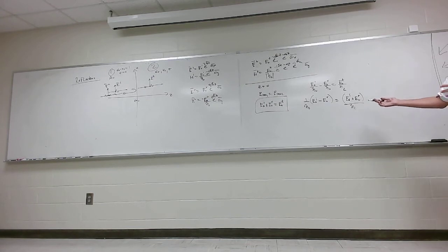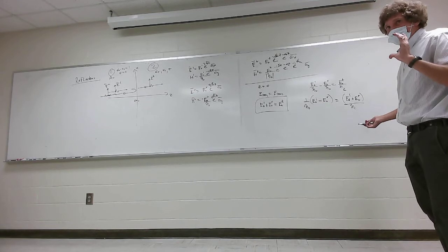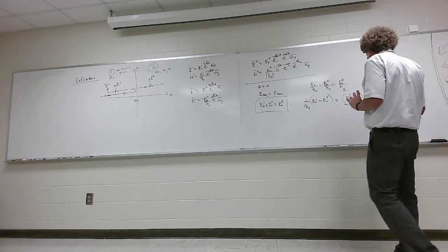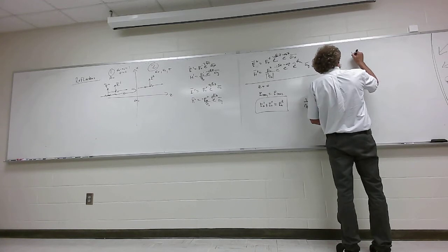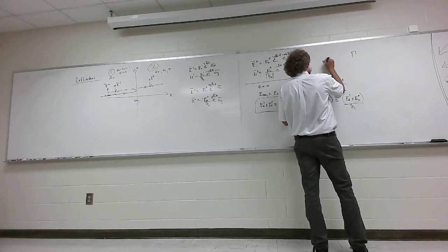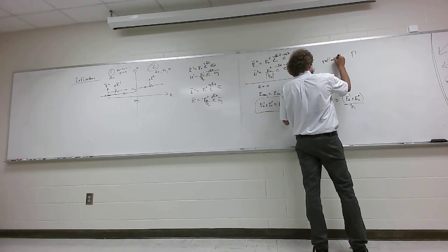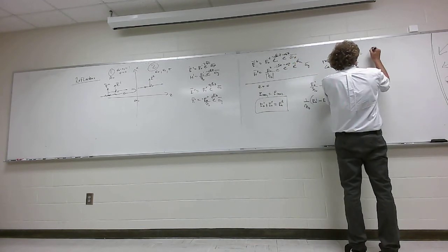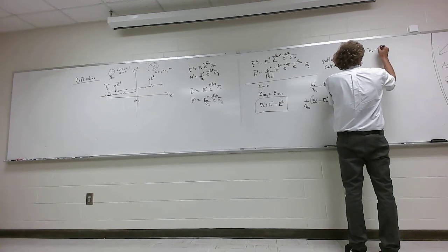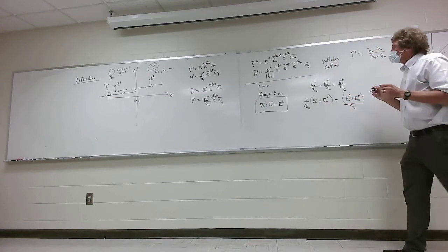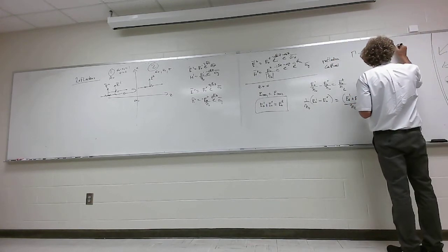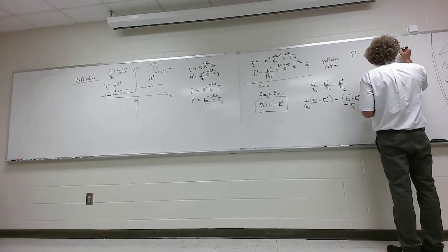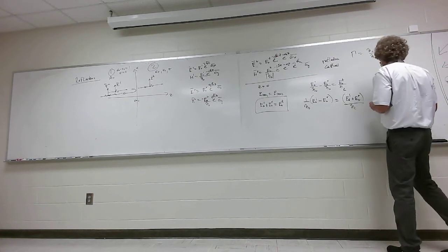But we don't really care about either one of those unknowns by themselves. What we care about is the ratio, and it's called the reflection coefficient. Put this down here. It's gamma, and that's eta 2 minus eta naught over eta 2 plus eta naught. I'm going to explain something. This reflection coefficient is the ratio of the reflected wave's magnitude to the incident wave's magnitude.